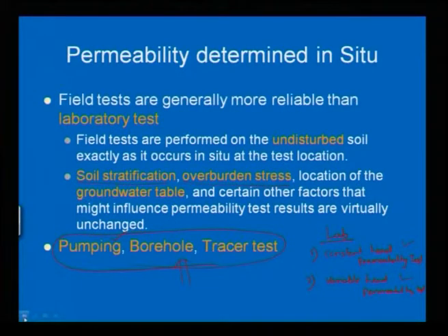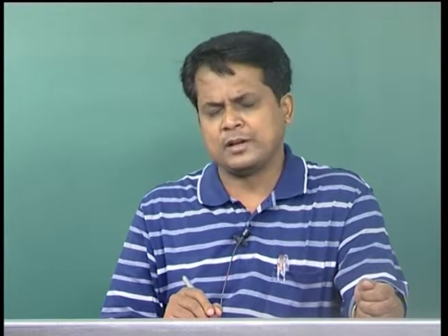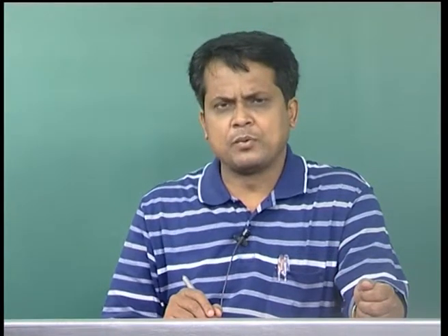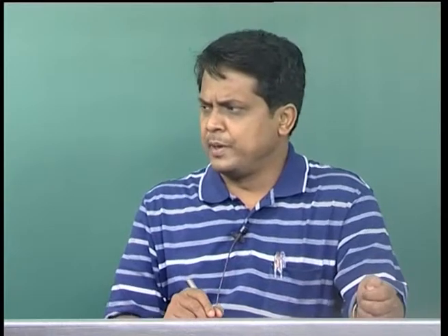Another is the borehole test, which I have not written there. By making a borehole, you collect the discharge of water over a period of time, and in that way you can also find the permeability in the field. This is all about the tests we generally do in the laboratory and in situ, the drawbacks of the laboratory, and the advantages of doing it in situ.